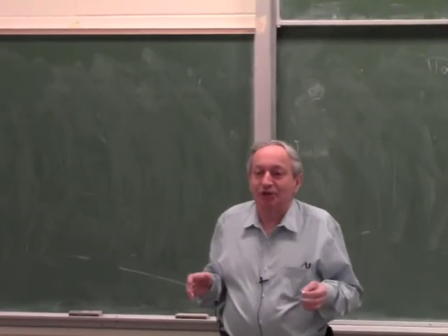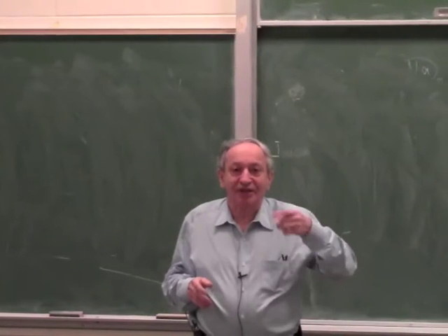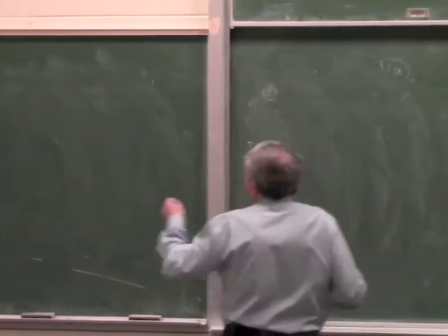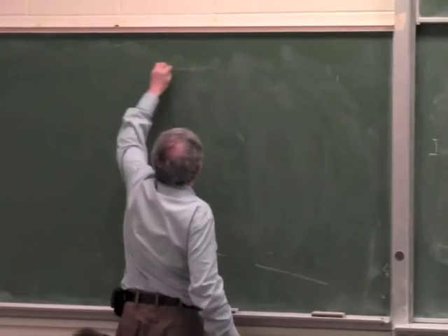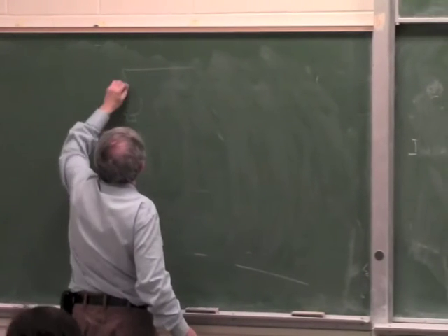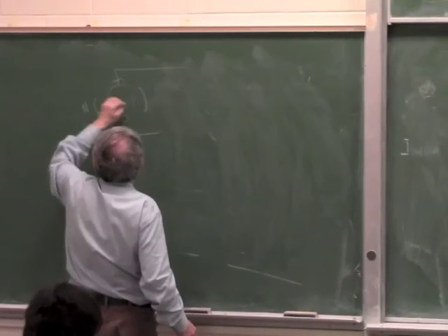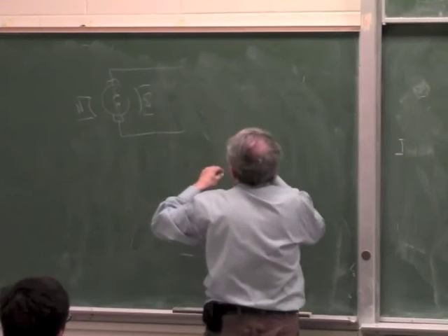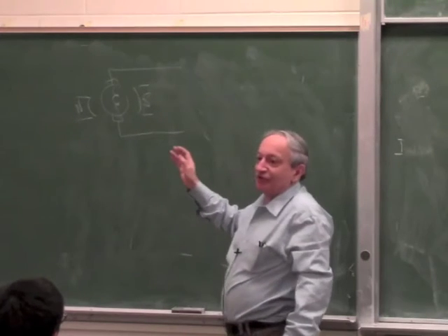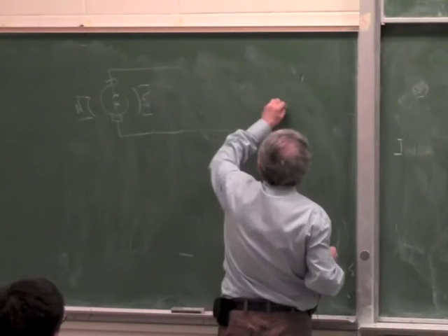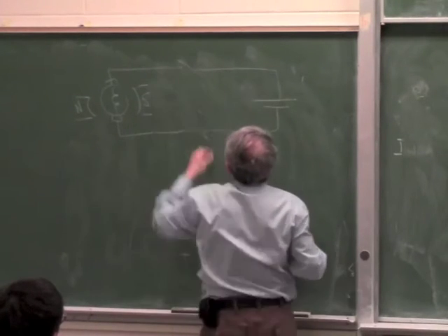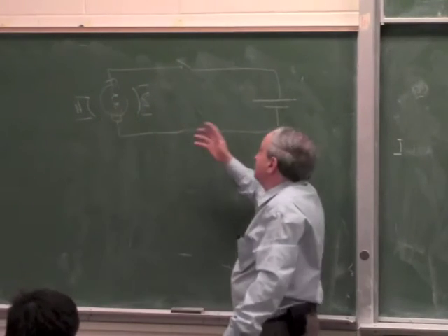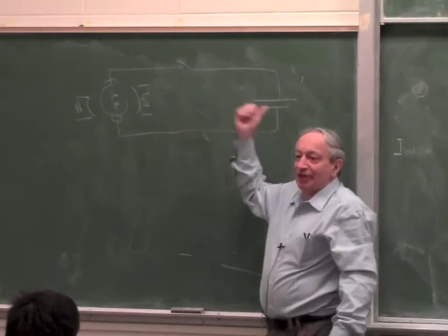because a DC motor, especially PMDC, if you just drive it, it becomes a generator. So there's nothing to do. So in all regenerative braking schemes, let's say you have a PMDC, you have to have a DC to DC converter, because if it's run from a battery, and the battery has a certain voltage, to do regenerative braking, you have to generate a voltage here which is higher than the battery voltage, so the current will flow backwards.